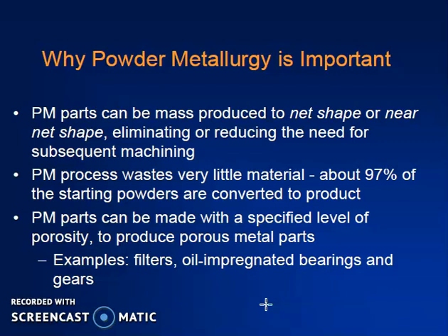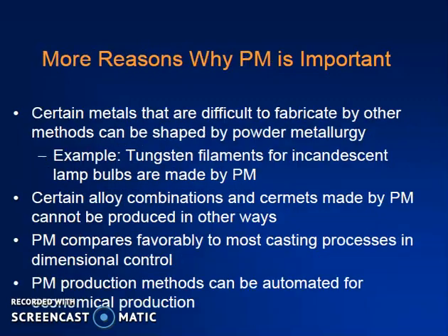Normally by any other manufacturing process we cannot produce porous metal parts, but this is the technique by which you can produce porous metal parts. Examples are filters, oil impregnated bearings and gears. So, where we require lubrication, that lubrication is achieved by this porosity in the product. Then more reasons why powder metallurgy is important.